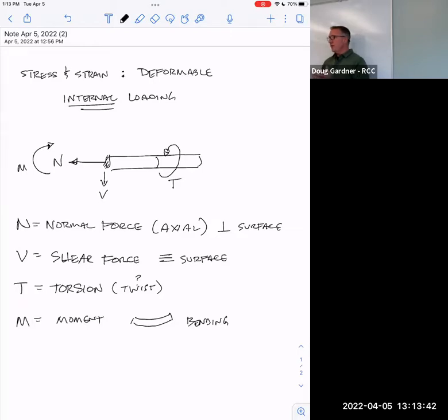It breaks some part that costs $10, which is actually awesome. It's a brilliant idea. So the U-joint is designed to be a break point, but it also lets you change direction, because usually an axle has to be straight. But what if it comes out of the engine and then the wheels are a little higher? Well, it can actually be a different angle, and this rotation is still connected to that rotation. So U-joints can also do that.